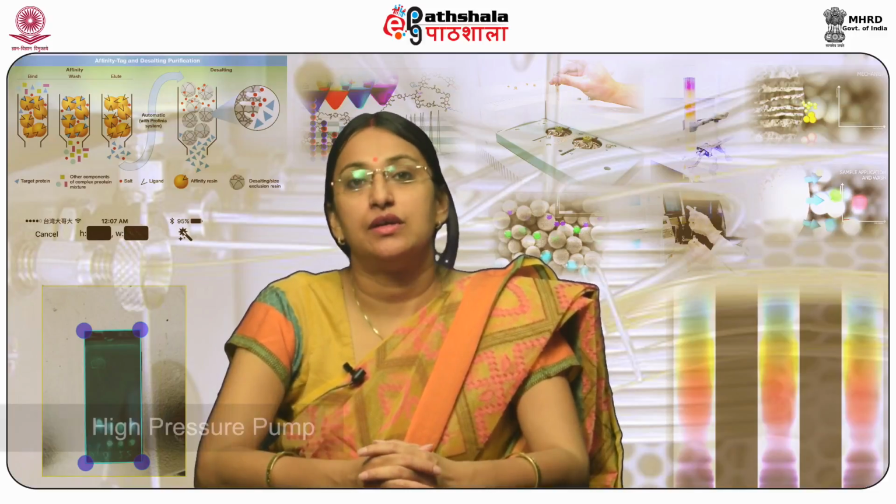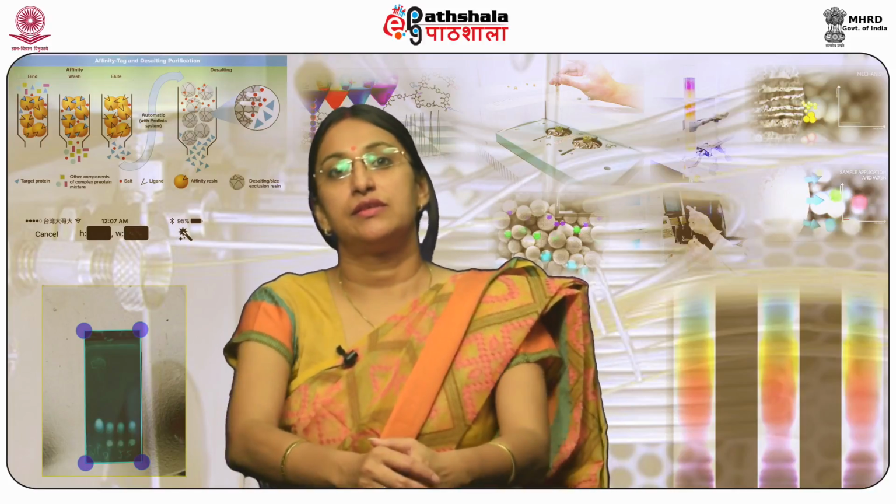High pressure pump. A high pressure pump is enabled to aspirate the solvent or mobile phase from the solvent reservoir and forces it with pressure through the injector, column and detector. The mobile phase has to pass through the stationary phase inside the column, which may consist of a compact bed of adsorbent material or ion exchange resin or a microporous packing material. This requires appropriate pressure to force the mobile phase through the compactly packed column and at the same time dissolve the analytes. The pump efficiently provides operating pressures ranging up to 6000 psi, sufficient to overcome the resistance to solvent flow